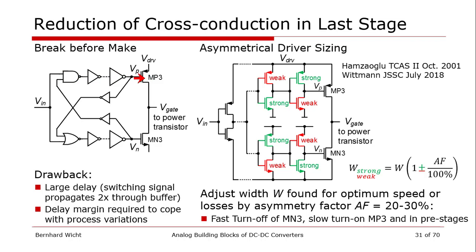That works quite nicely, except that the signal propagates 2 times through the driver chain here. And likewise in the other case here, vice versa. And that's why the process variations and all tolerances have some impact here, and in the end you will always need to do some over design, add some design margin, and that's the drawback. So for general purpose it works.